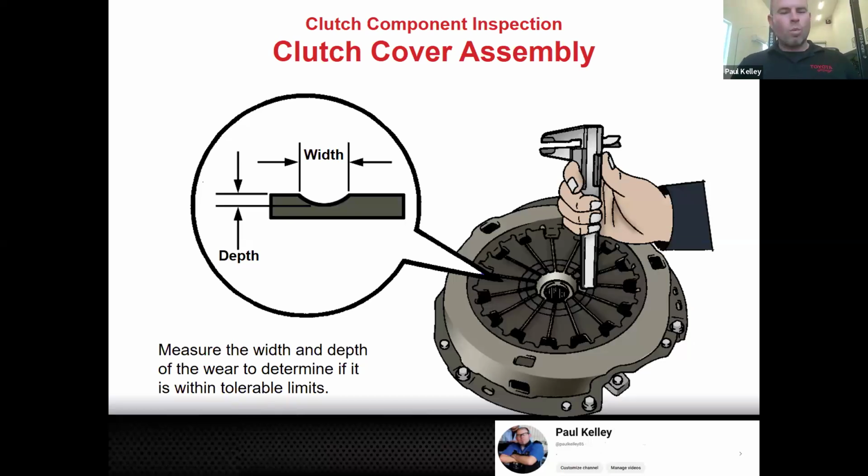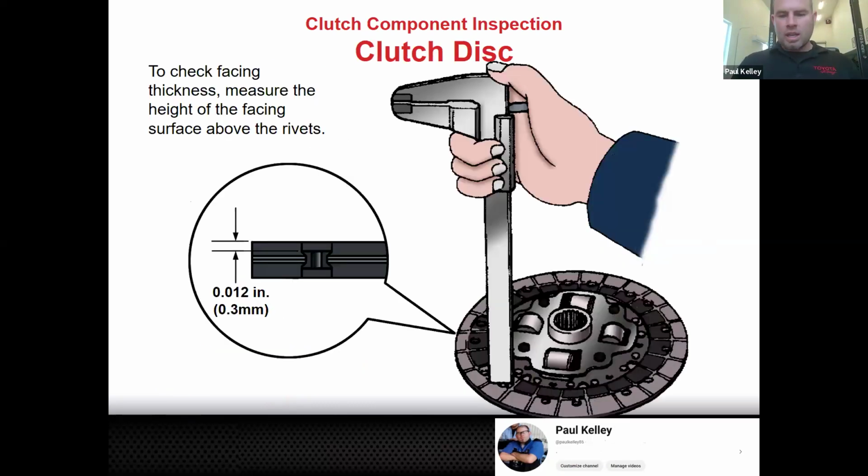According to me, why? Even if it's good right now, a clutch should last 100,000 or more miles. So if you don't think it's going to make it all the way to 200, no, you do it now. This is the time to do it. This makes a lot of sense to do it. Okay. So by all means, inspect all this stuff, but I'm going to tell you again and again, if you go in there to do something with a clutch, do the kit. Do the kit because you want it to last all the way until the next interval, which should be over 100. For me, I get 200,000 miles out of a clutch because I barely press the clutch anyway.